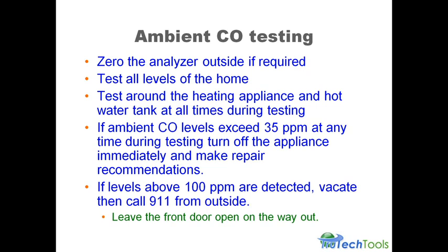Above 35 parts per million, not safe. So shut the appliance down. As a contractor, I don't care whether you're BPI or ResNet or HVAC contractor, you have the right to shut off the appliance and tag it that it's not safe. You can shut it off, put a red tag on it, and say do not operate, unsafe to operate. You have that right as a contractor to do that. I don't care what kind of a contractor you are, you have that right.